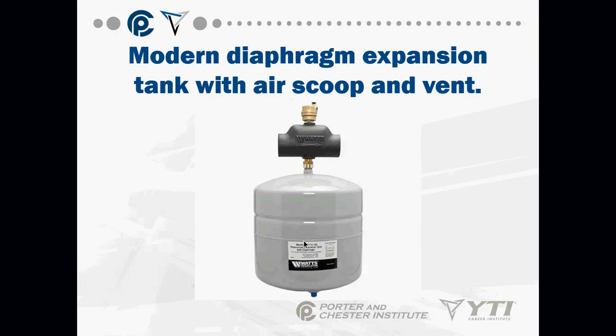And if there's any air in this air scoop, it will scoop up that air and shoot it right out that air vent, right out the top. Usually when it's happening, you kind of hear a small little hiss sound coming out of it. That is perfectly normal. As long as you do not see water dripping out of your air vent, you are still good. If you start seeing water dripping out of this air vent, it is no longer good. It needs to be replaced.